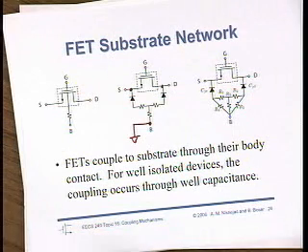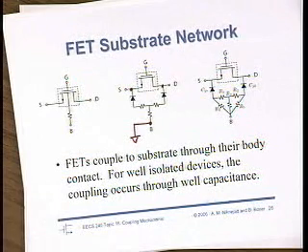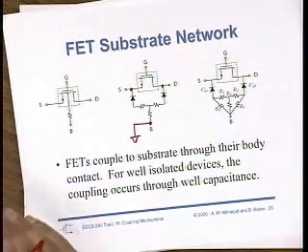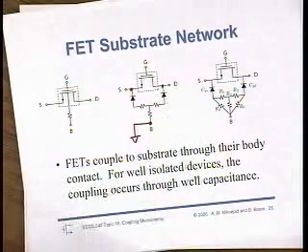Unfortunately, your SPICE circuit with 10 transistors would turn into a SPICE circuit with 10 transistors and 100 million resistors. And it would basically take 10 weeks to simulate. So doing a brute force approach of having a substrate doesn't work. You have to do something more clever.